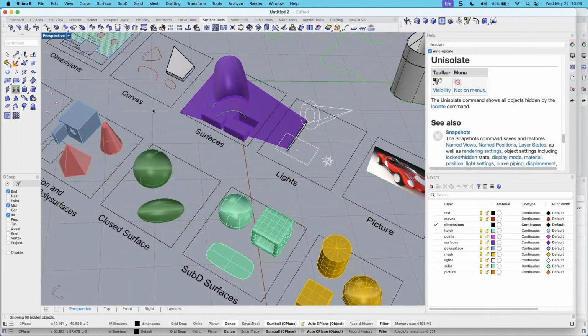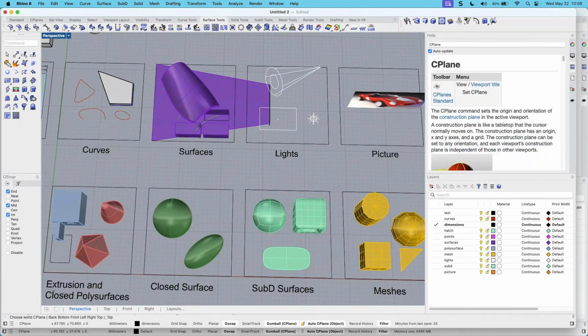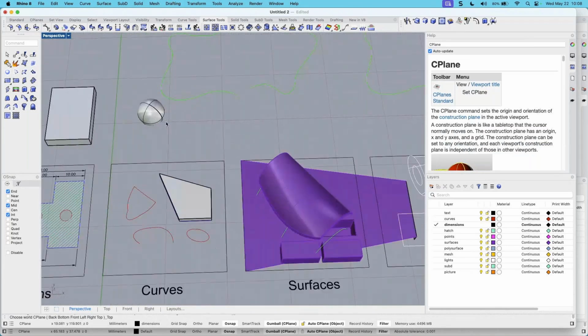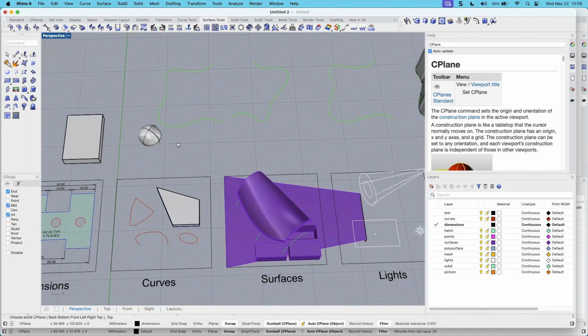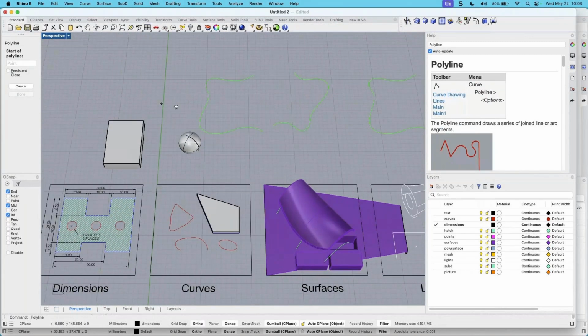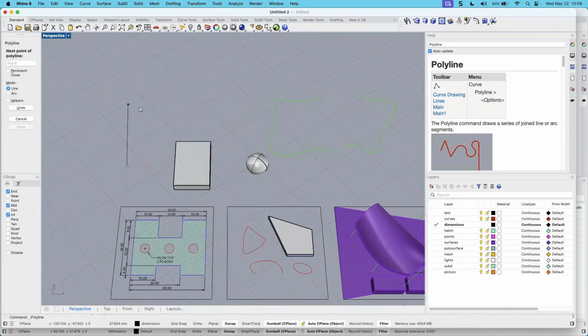Okay, I think you have everything that we need here in order to put together the next model. And there's just one point I want to make about drawing curves, and that is in Rhino, we may be in millimeters in this model, but if we know what the distance is in another unit, we can type it in.